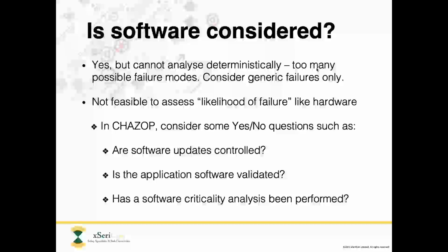So if the failure cause, for example, was a CPU failure in the control system, then we may need to assume that every safeguard that requires correct operation of the control system becomes unavailable. So that could knock out alarms, control loops, DCS-based trips, and any other kind of active safeguard that relies on the operation of the control system.